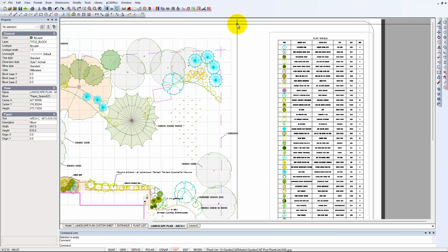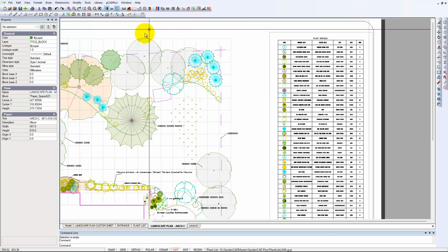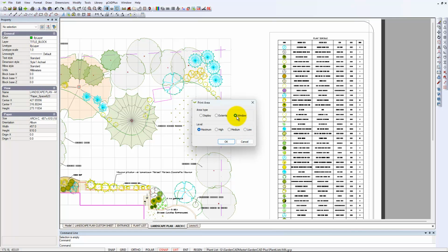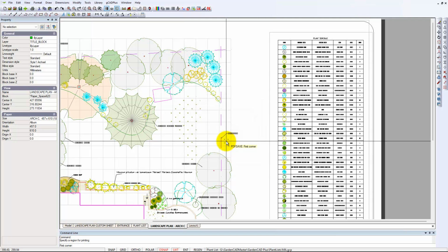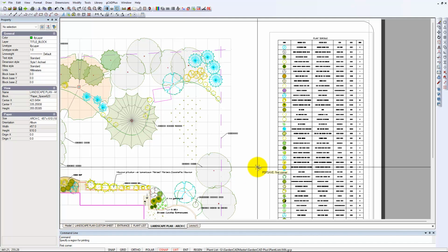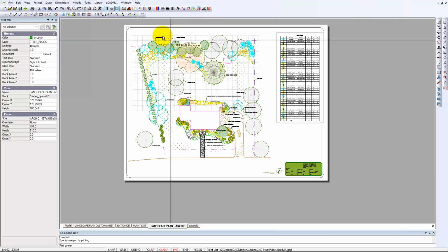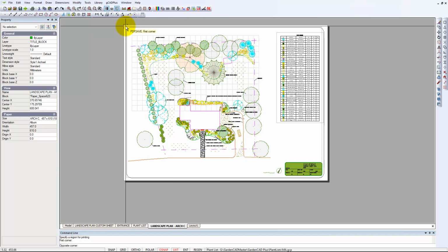Let's do a very quick test. We're still not at the stage of printing a very high resolution view of this design. The quickest way to check things is to save as a PDF. We'll go window it and a maximum, and we'll be asked for the first corner of our print. I'll center it, pick a corner here, and come down to there,